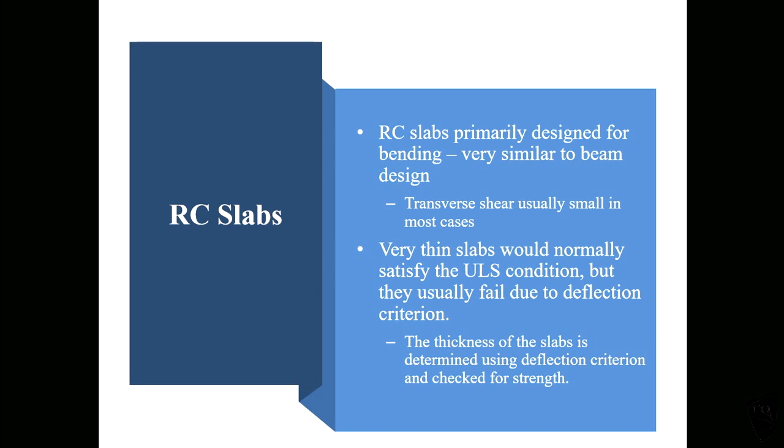We will also check for deflection. In slab design, normally the deflection is the more complicated or problem parameter. So if the deflection check passes, your design is almost done, because the flexural design is quite straightforward.